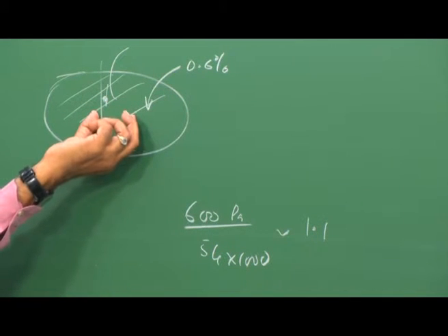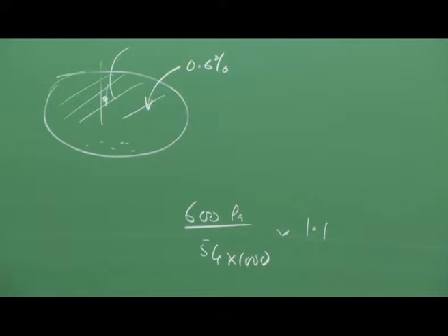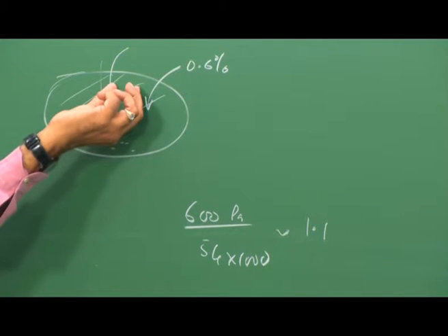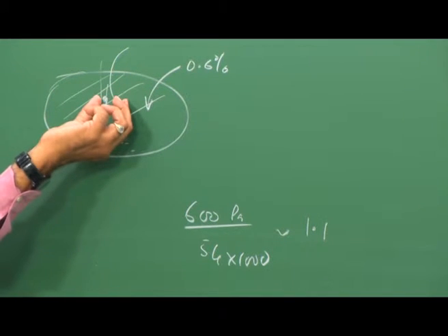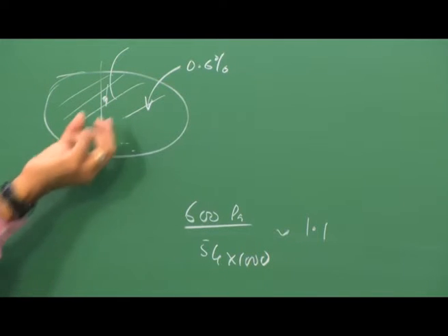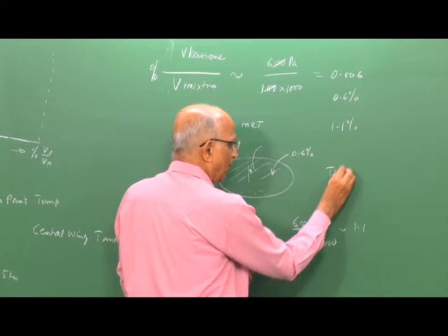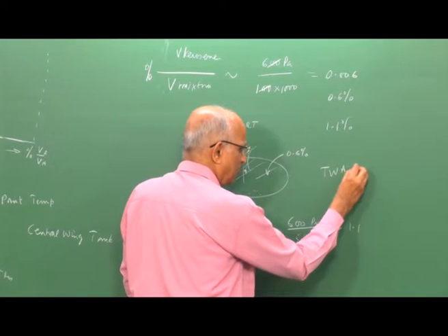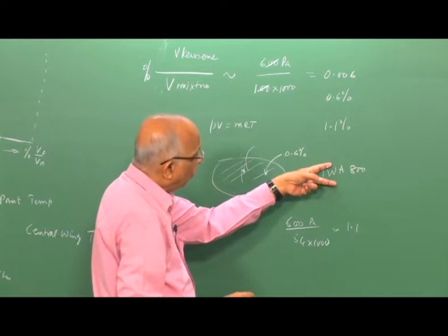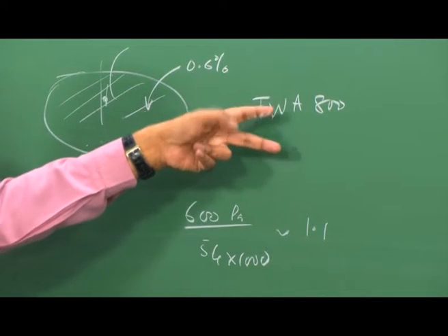But for the present, from what we learned about the lean flammability limits, we are able to tell ourselves that at altitude, when the ambient pressure decreases, I can form a mixture which is flammable, and therefore, there could be a catastrophe. And this is what happened in this particular flight. This particular flight was the TWA, Trans World Airlines 800, which was from New York to Rome, and